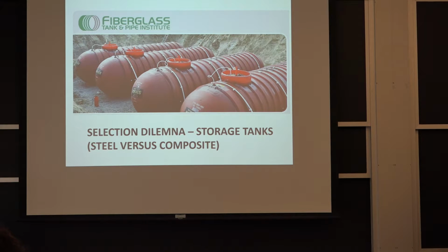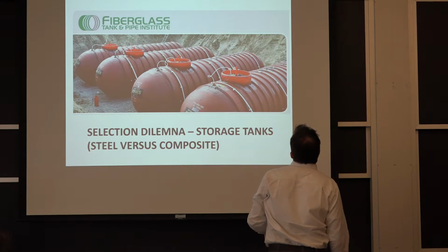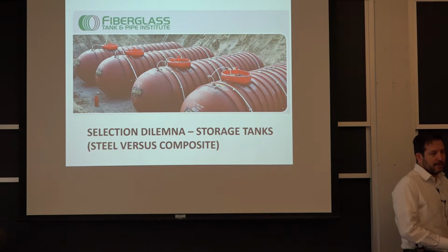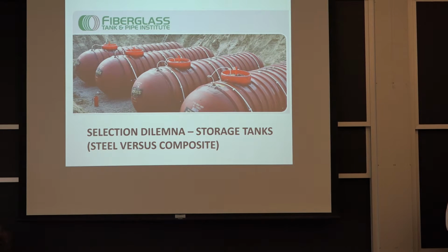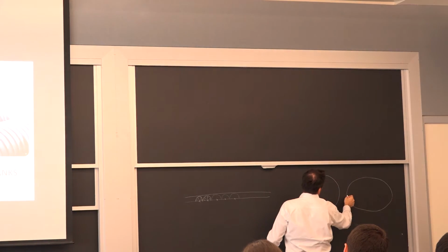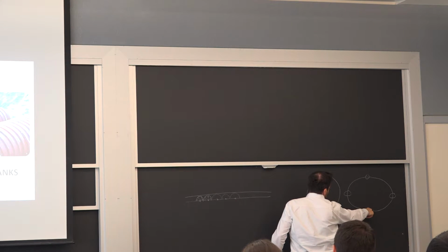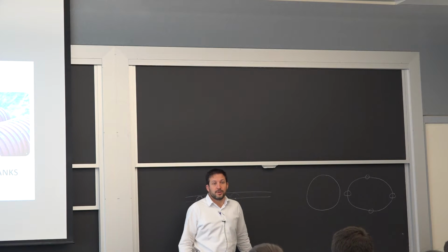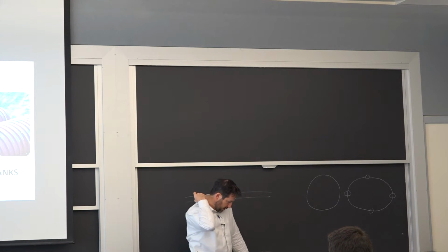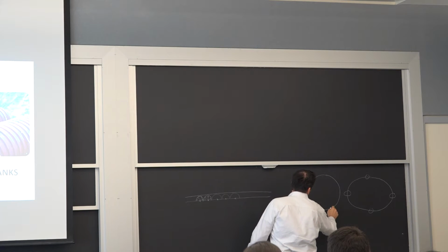Just a little bit on how it works with the composite is you can make use, you see these ribs around the circumference, and one of the issues with an underground storage tank is the weight of the dirt and cars and trucks that are going to be right over it at any point in time. So you need to have this crushing resistance, and we've seen that on some of the previous images. So the failure mode for a tank or a drainage pipe is it starts round, and then it turns into an ellipse over time. And by doing that, you get a lot of stresses here, here, here, and here. One of the more important ones here is you get tension on the inside at the bottom. That's not really cool. So when you have to put these tanks into the ground to make sure that they have their useful life, you have to support it with good aggregate here to minimize.